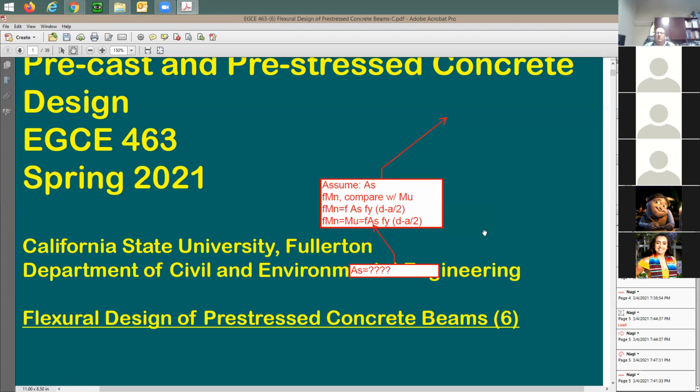Second method of conventional concrete, you're going to be setting up phi Mn min equal to Mu, and this is going to be a numerical value. Based on this, you solve for As. Now you need to know how much As is needed in square inches. Now I have it. Now I'm going to say I'm going to be using number 7. Number 7 rebar has 0.6 square inches of cross-section area. Let me figure out number of rebars. Let me now check phi Mn min and be sure that it goes above Mu. This is going to be now the second method.